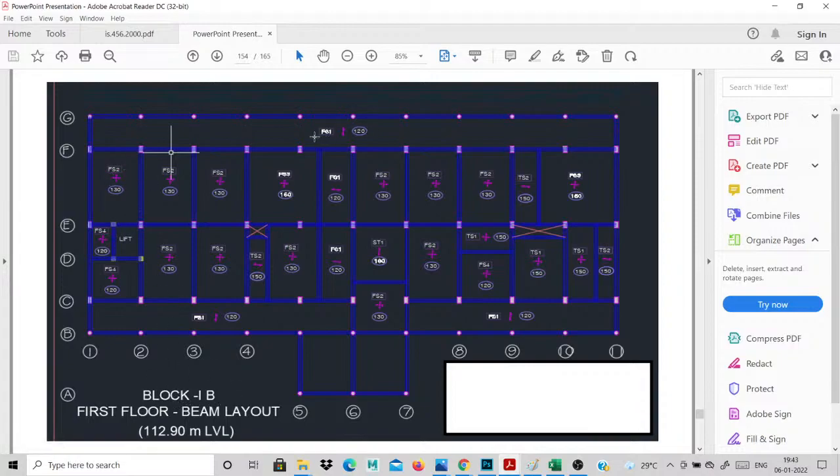This is our slab. I already told that for a one-way slab, you mention the symbol for the direction of two sides and the thickness. This is our two-way slab. A two-way slab has load direction into four sides. This is a one-way slab, with two sides. This is four sides. The thickness will be mentioned, and then the slab name also. This is our slab layout.